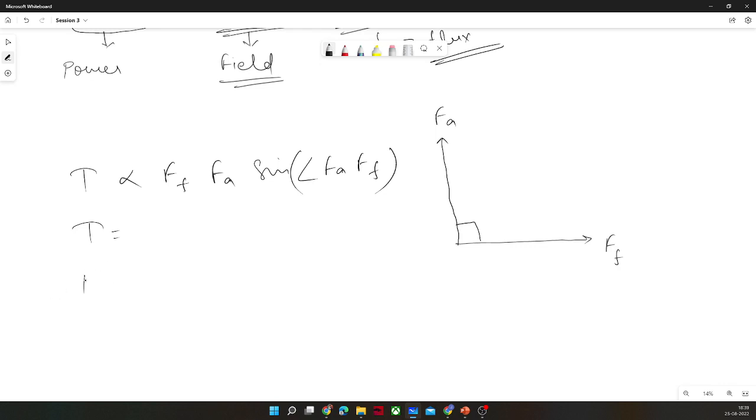And generally from the power equation also, you can see EV by XS sine delta, if armature resistance is ignored. If delta is 90 degrees, you have maximum power, corresponding to maximum torque. So I will explain this phasor now since I have mentioned it.